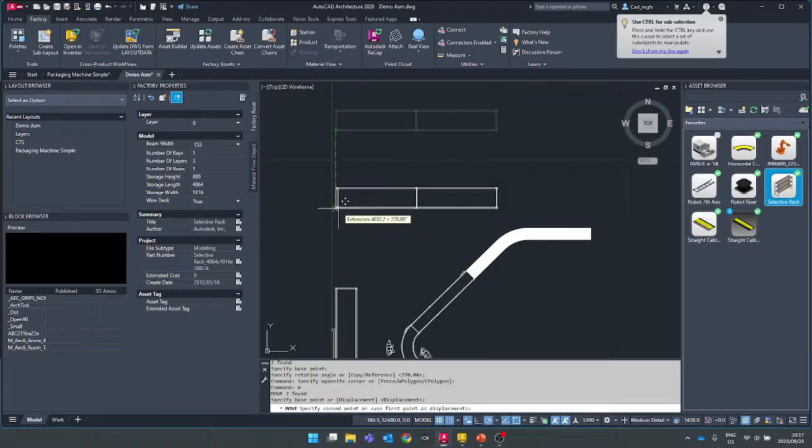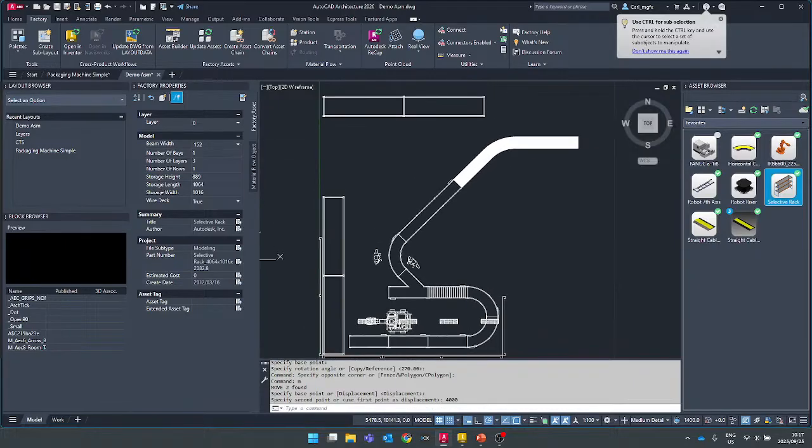Let's go about 4 meters and get that into a new position. So just using, once that asset has been dragged and dropped in, just using the standard AutoCAD commands to then position that block. And also when selecting the block, we are able to make changes to the block properties itself, model geometry, as well as properties for that, or view the properties for that block.